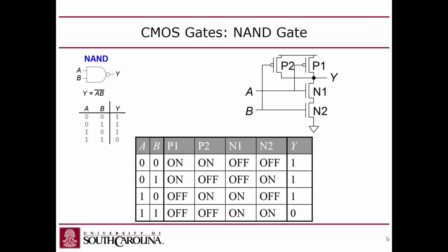So let's see, how do we minimize these? So the idea is that you have one option, so these are all combined with ORs here, right? So if you have A and B are both 1, then those would be on a parallel branch, and if they're both 1, they would both be turned on, and you'd pull down to 0. You guys with me? Now these two guys would be in parallel up on the pull-up network, right? All right. So then, let's see. On the other hand, if you've got not A, not B, let's see.